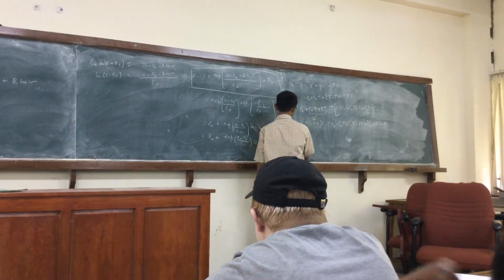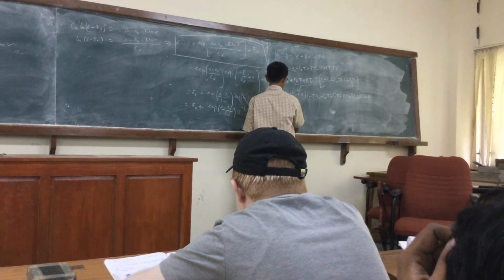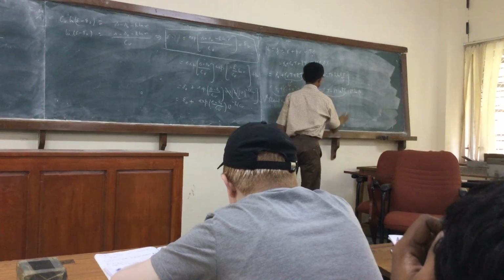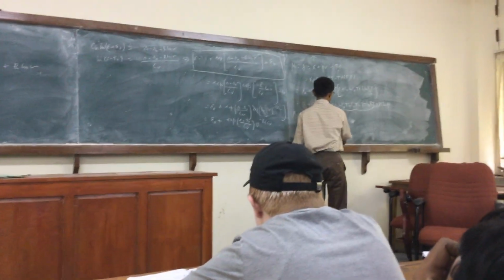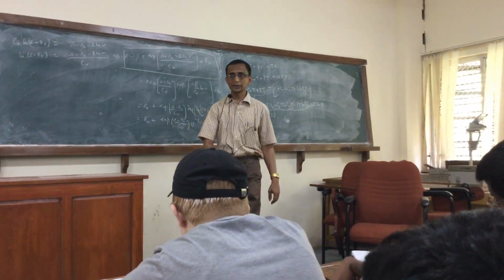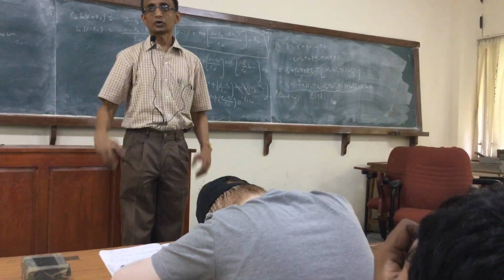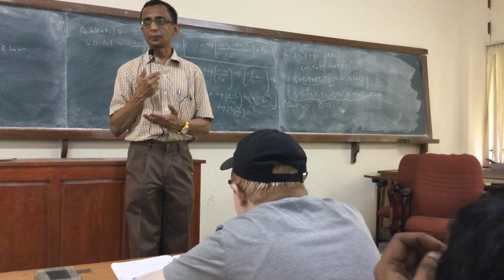So, for the ideal gas, I can now call this entire group of functions some function of temperature. Of course, it has some parameters, the universal gas constant and the Cv. So the form makes it clear where the Cv comes in.